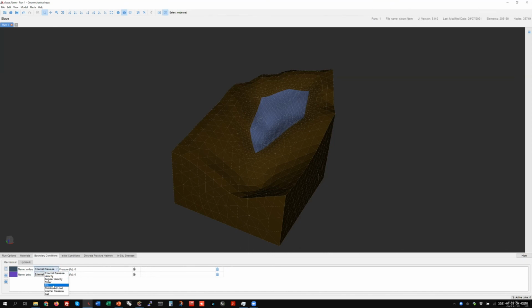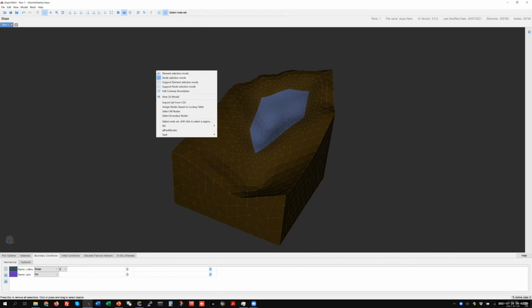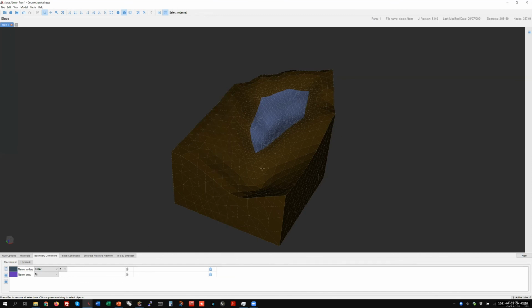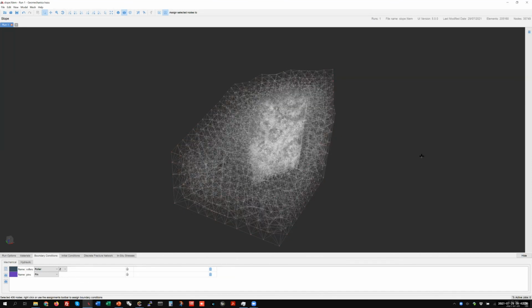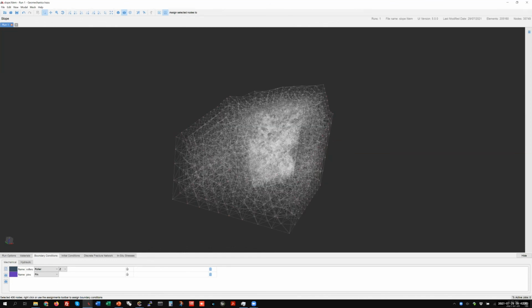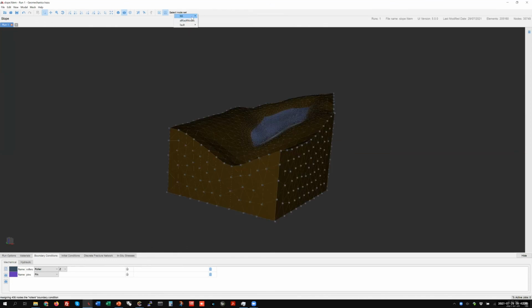Okay, so rollers, this will be a roller that allows movement along Z as well as pins. So then you select, I don't know if I can take this up, no. So as I said, you could also select from here or just by right click. So node set 2, I believe, were the nodes on the sides. So you see the nodes on the sides are now isolated for easier viewing. So you could assign them here to rollers. And then you could select node set 2.